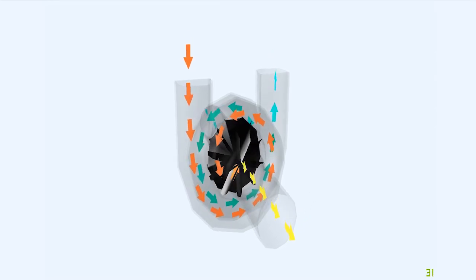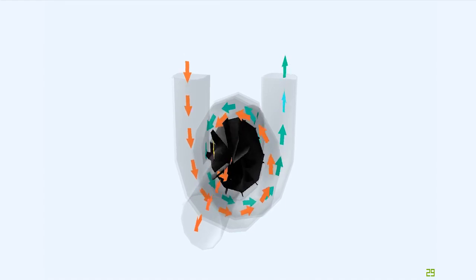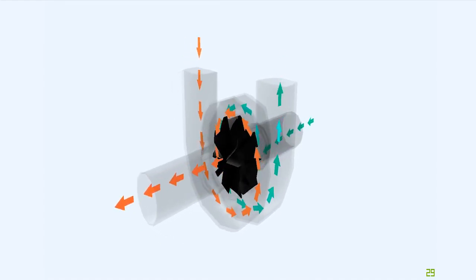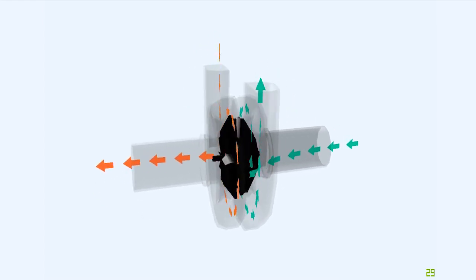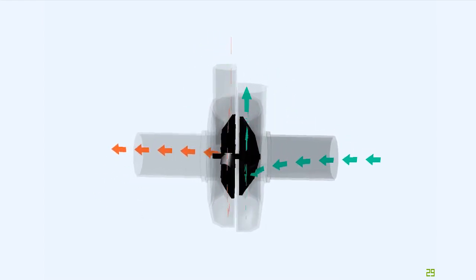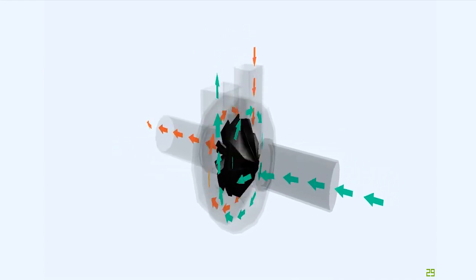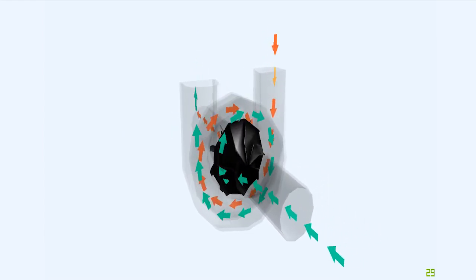Exhaust gases pass through nozzles and are guided onto vanes on the turbine wheel, causing it to rotate. The gases then pass between the vanes and are exhausted overboard. As more exhaust is passed over the turbine, it will accelerate, therefore driving the impeller faster. Thus, the pressure ratio of the compressor and its output increases as the turbine speed increases.